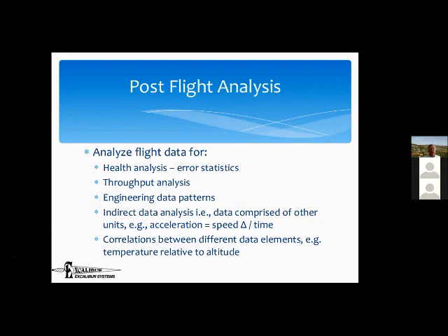We once actually had a case in which a client was having trouble with his communications and didn't understand why, so he asked for our help. It turned out that every time his plane went above 20,000 feet, it stopped working, just because some parts were freezing. And the only way to see that is to look at the data and look at all the other data at the time that the error occurred. And if you consistently see that the altitude is above 20,000 feet, that tells you something. So it gives you a direction for what it is that you need to fix.